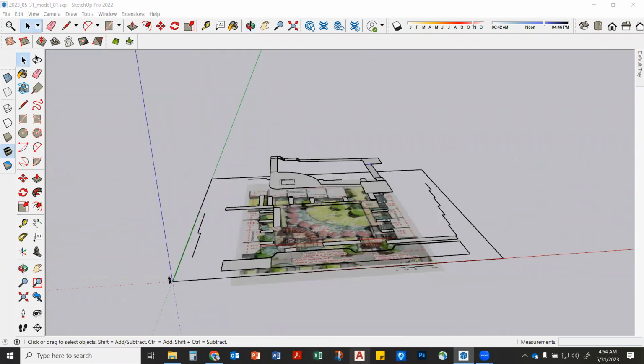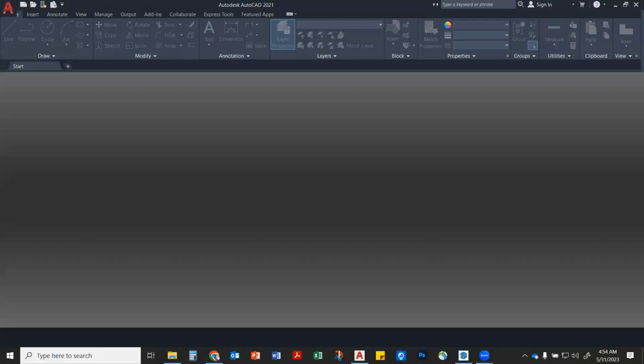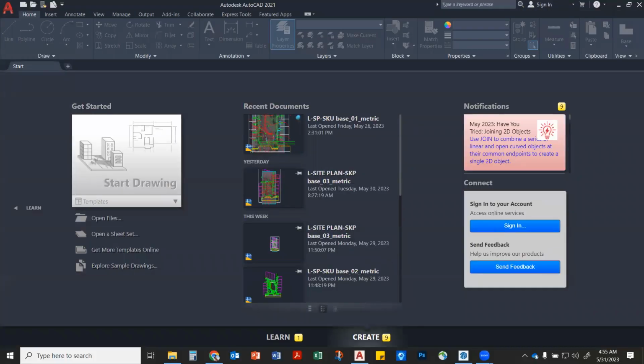Remember when I did all of that CAD drafting for you guys? And so we have a CAD block that has all of the closed polyline walls on it, okay? So we're going to import that. How do we do that? File, import, yeah?